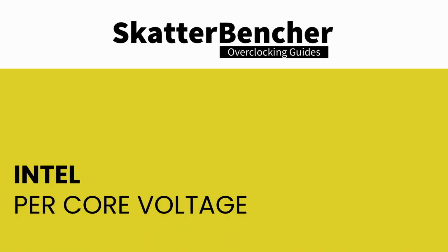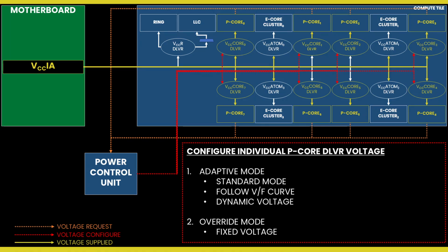Intel per core voltage allows you to set a specific voltage for each P core and E core cluster of your Arrow Lake CPU. Obviously, this is only possible when DLVR is enabled because you're configuring the DLVRs. Similar to the global voltage mode, you can configure the per core voltage in adaptive mode and override mode, specifying a voltage for the defined per core ratio limit or across the VF curve respectively.